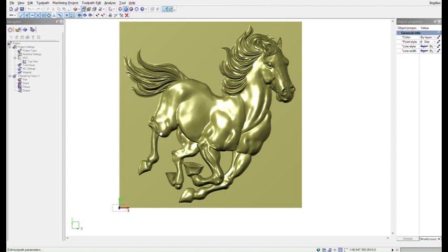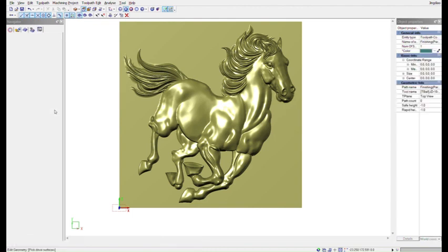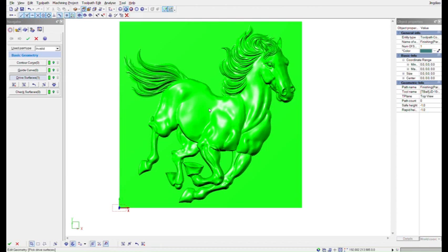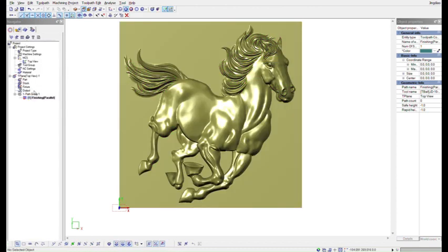and now almost all the parameters and setup are done. The others are optional things, you can try them later. So the basic ones have already been explained. And then save. Now you can see that a tool path file is created here. Then you can right click here and give the geometry, you select that model here, and okay. Now almost finished. Now again right click here and regenerate. Then it is going to create the tool path according to our preference.